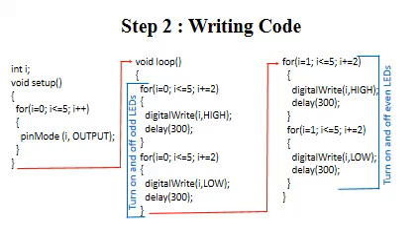Now it's time to write the logical instructions in Arduino software. We need a variable for storing the pin numbers. Here I have declared a variable named i. I have not given any value in it. It will get the values from the for loop. In the void setup section, I have written a for loop which repeats 6 times.